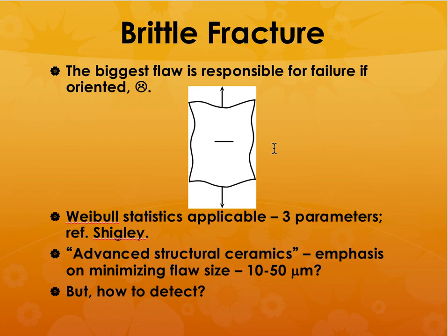So suppose you have a sample that broke at say 10 KSI and another sample that broke at 90 KSI. The average of your failure strength is going to be approximately, so it ranges all the way from 10 to 90. So depending upon the number of samples that broke, you will get a certain value. Say for example, for argument's sake, let's say 50 KSI. And the standard deviation for your 10 samples is going to be plus or minus 20 KSI.